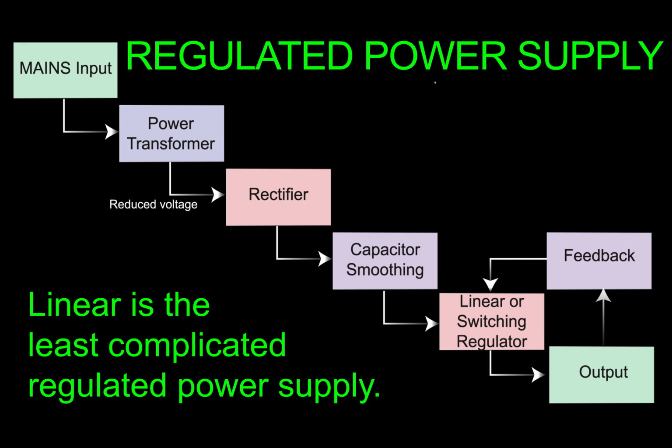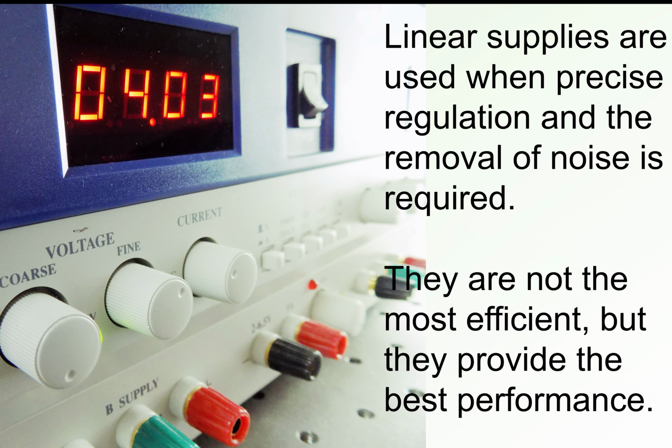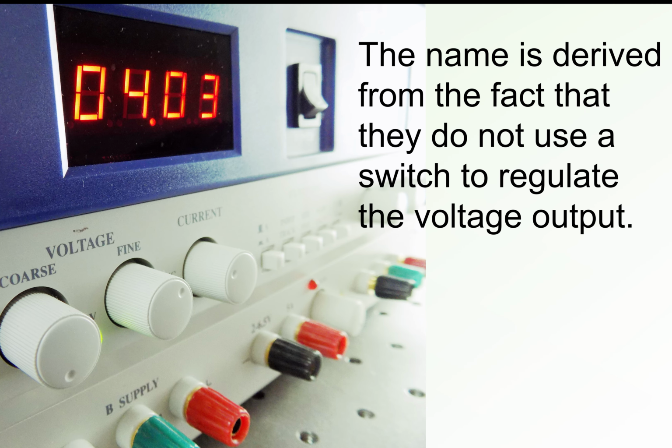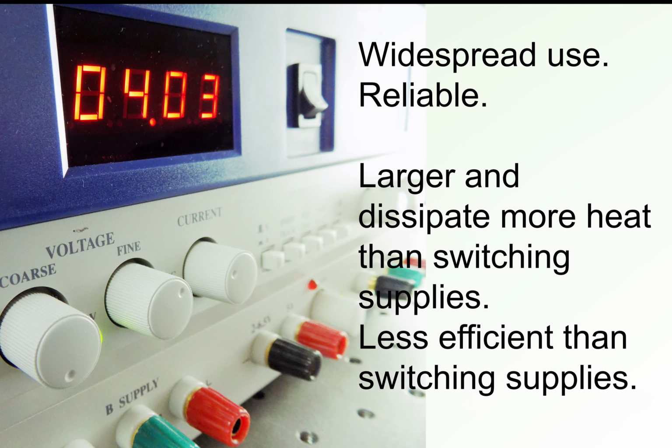Of the three basic regulated power supply designs, linear is the least complicated system. Linear power supplies are used when precise regulation and the removal of noise is most important. While they are not the most efficient power source, they provide the best performance. The name is derived from the fact that they do not use a switch to regulate the voltage output. Linear power supplies have been available for years, and their use is widespread and reliable. The disadvantage to linear power supplies is that they require larger components, hence are larger and dissipate more heat than switching power supplies.